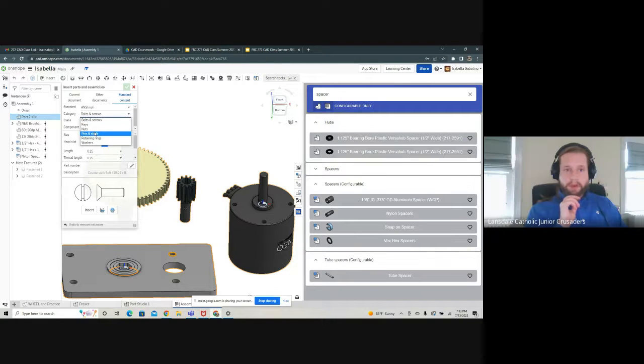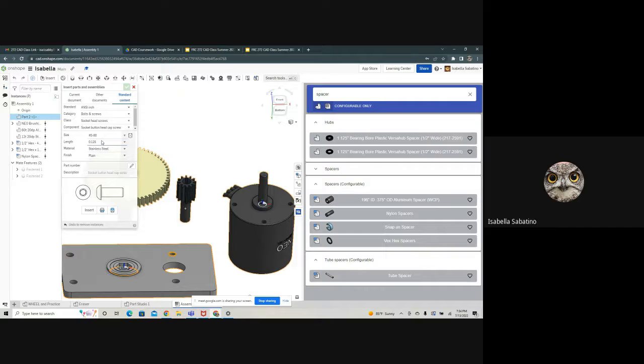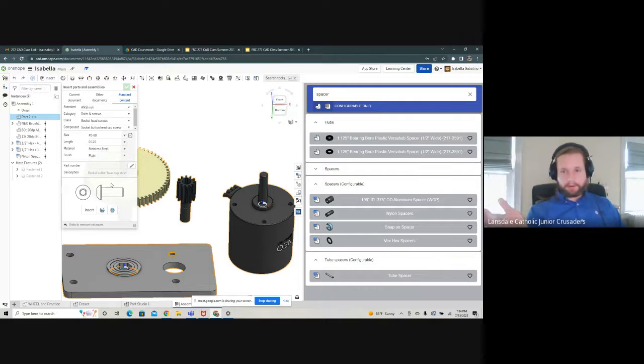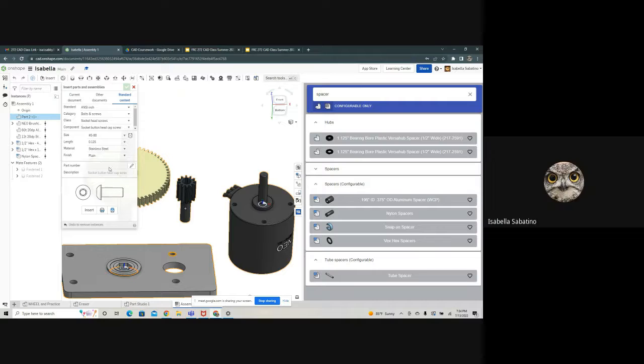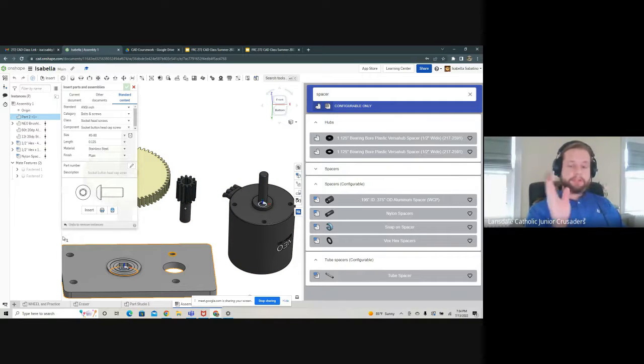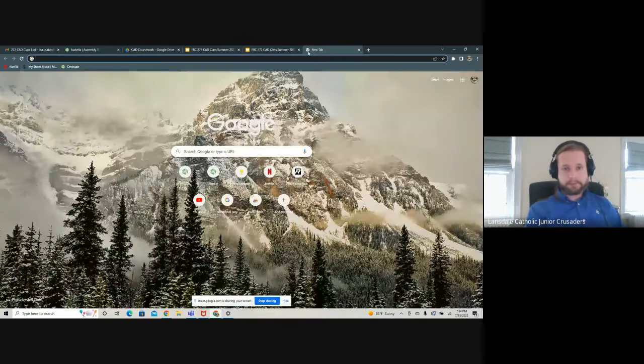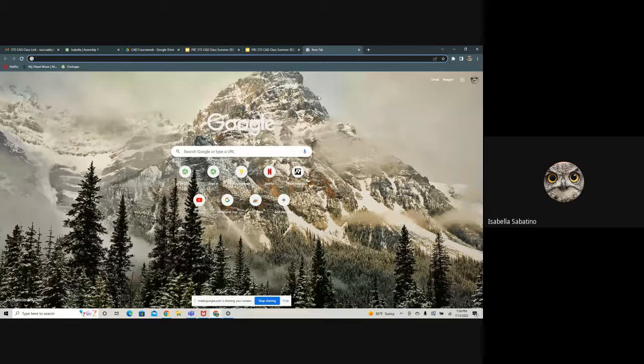Okay. So you probably want bolts and screws, and socket head is probably what you're looking for. Yep. Thank you. You could do a button, or a regular socket head cap screw, or you could do a flathead screw if you wanted to. Okay. And another tip, you should look on the manufacturing information page of the Neos, which is on REV's website, for what kind of thread goes into those motors. And then you should be able to pick the right bolt from that. Okay? Okay. Thank you. Cool.